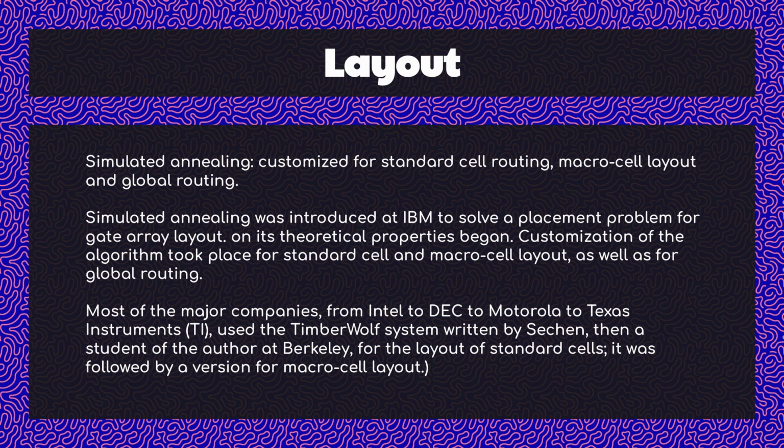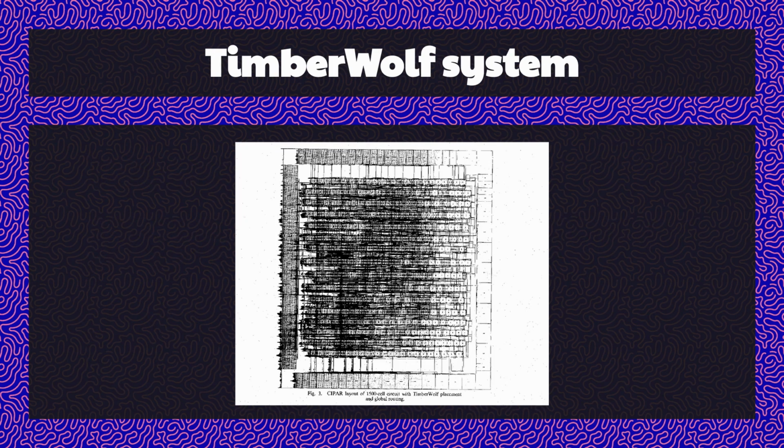It was introduced at IBM to solve the placement problem for gate array layout. And most of the major companies, from Intel to DEC to Motorola to TI, actually used the TimberWolf system that was written by Sechen, who was a student of Sangiovanni-Vincentelli at Berkeley, for the use of standard cells. It was also followed by a version for macro cell layout. This picture is an example of a circuit that was designed with the TimberWolf system. The TimberWolf placement and global routing tool was used to make this 1500 cell layout.